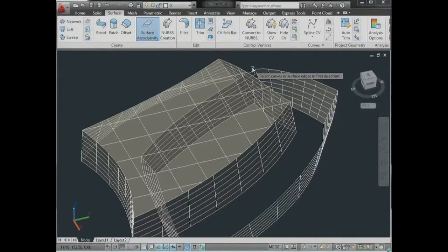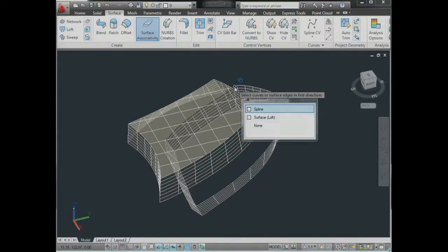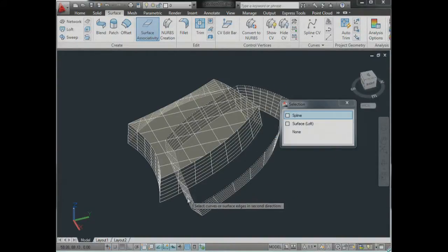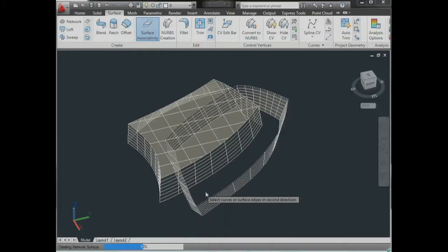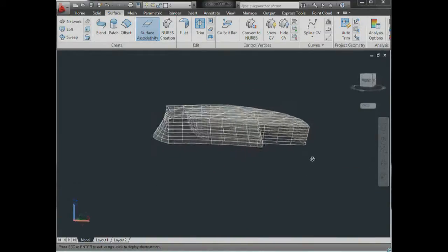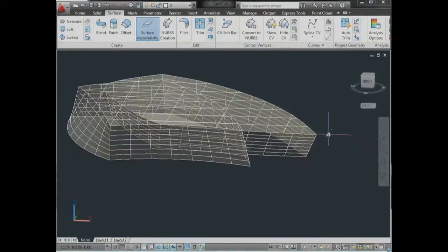And I could also have worked with the network surface. For example, in this case, I'm just grabbing these surface edges, and as you can see, in AutoCAD 2011, when I grab any place in which there are many elements coexisting, I have selection cycling to go through it. So there I go. I have my two bodies here, and I'm ready to keep modeling, keep working on it.